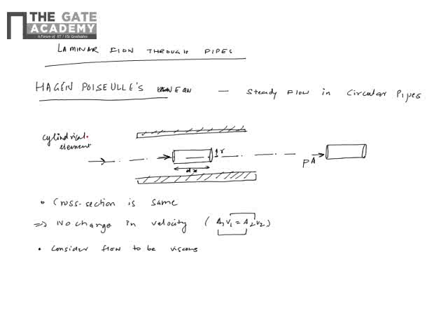So its area is pi r square, and here let's say the pressure is varying. So the pressure here, let's say, is P plus dou P by dou x into dx. How am I able to write this? The new pressure is this into A, the area being the same. How I have written this is by means of Taylor series. Taylor series basically says, if I know the pressure P of x, I can find the pressure at P of x plus h. P of x plus h is P of x plus h into dou P by dou x, or dP by dx, plus h square by 2 factorial into d square P by dx square, and so on.